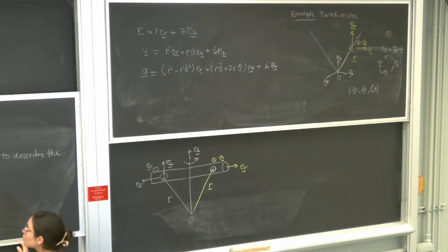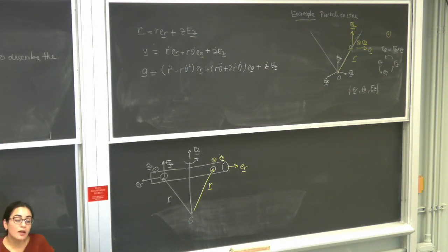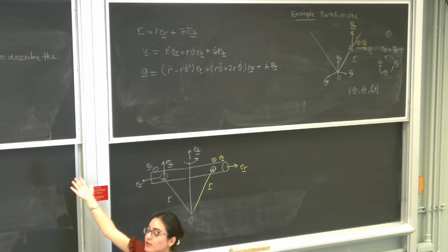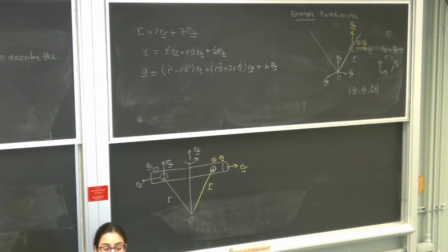So when I add constraints, I decrease the number of degrees of freedom, and they are replaced by constraint forces. For example, when I connected the 2 particles by a rod, I added a constraint, an equation to the system, but this constraint also adds an unknown, an unknown tension force between the 2 particles that I need to find. Oftentimes, expressing this constraint will help us solve for the motion of the system.